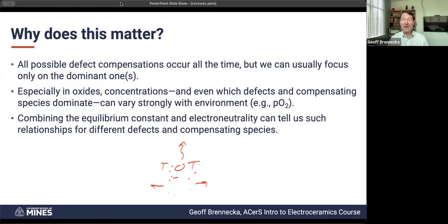So in both cases, you'll swell the lattice with those types of defects, and there's not a hard and fast answer, if this, then this. It depends on what the scenario is. In this case, I would measure the bulk density, because the lattice parameter is actually going to increase in either case.